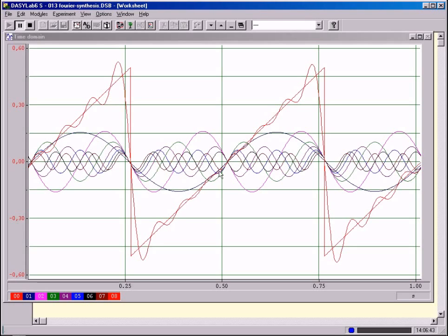This is very important. All periodic signals contain as sinusoidal components all the integer multiples of the base frequency as only these fit into the time frame of the period length t. The periodic sawtooth has 2 Hz. Therefore, the basic sinusoidal component has also the frequency 2 Hz. The next has 4 Hz, 6 Hz, etc. These are the multiples of the basic frequency.